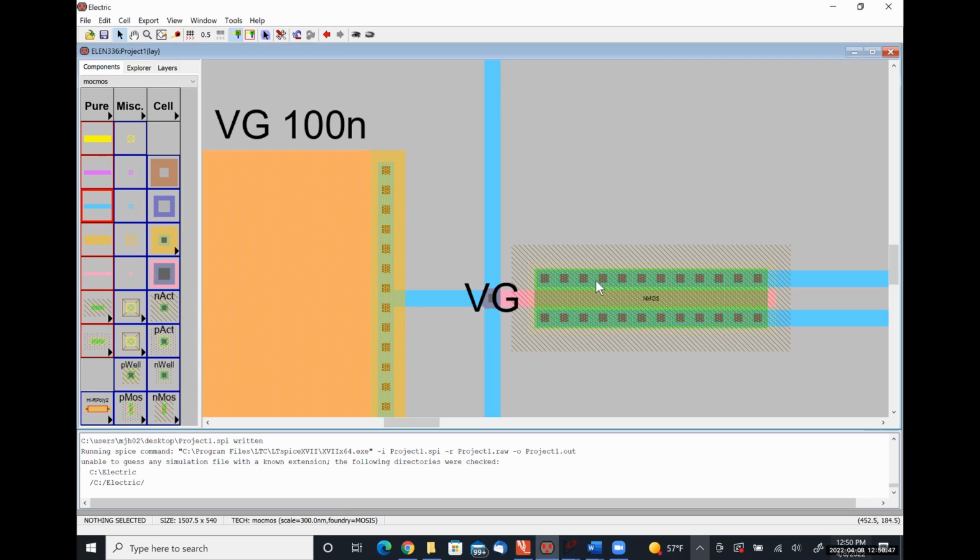So you don't really need to do that. The only thing I would really worry about hooking up a P-well for would be to do a guard ring around the body terminal, and we're not even bothering to do that here. And that sentence I'm sure means nothing to all of you.